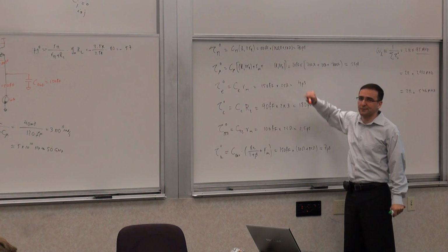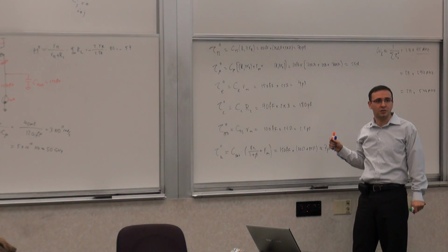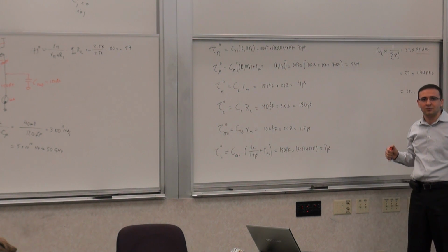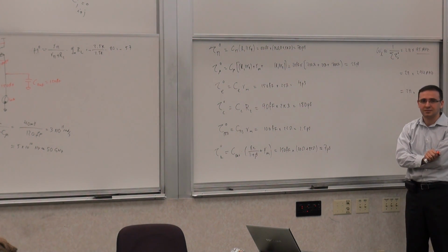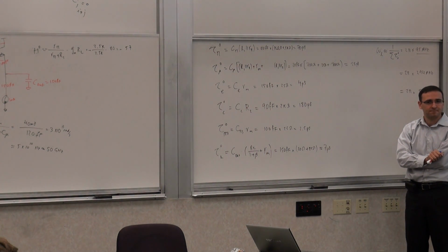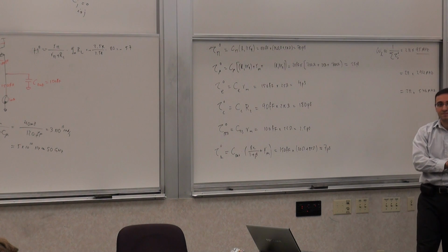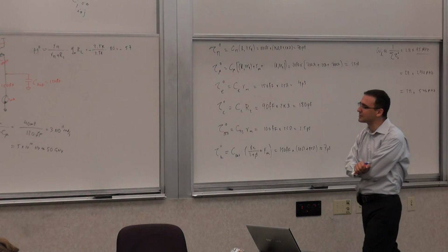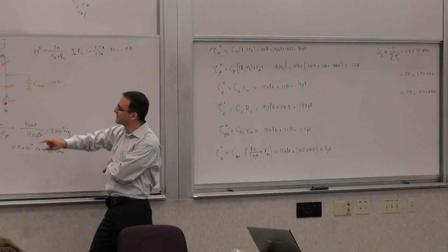If I were to fix this first, though that's not the right thing to do, how would I do that? What is the problem there? Do an emitter degeneration. But that kills my gain. Lower the sources. Use an active load as a resistor in degeneration. Use an active load as the resistance. Well, yeah, then this problem is still here, right?